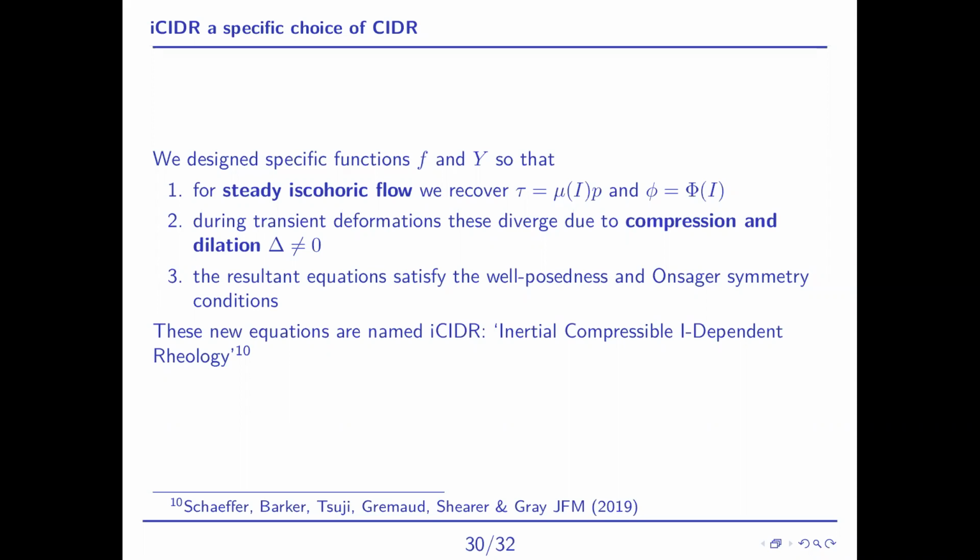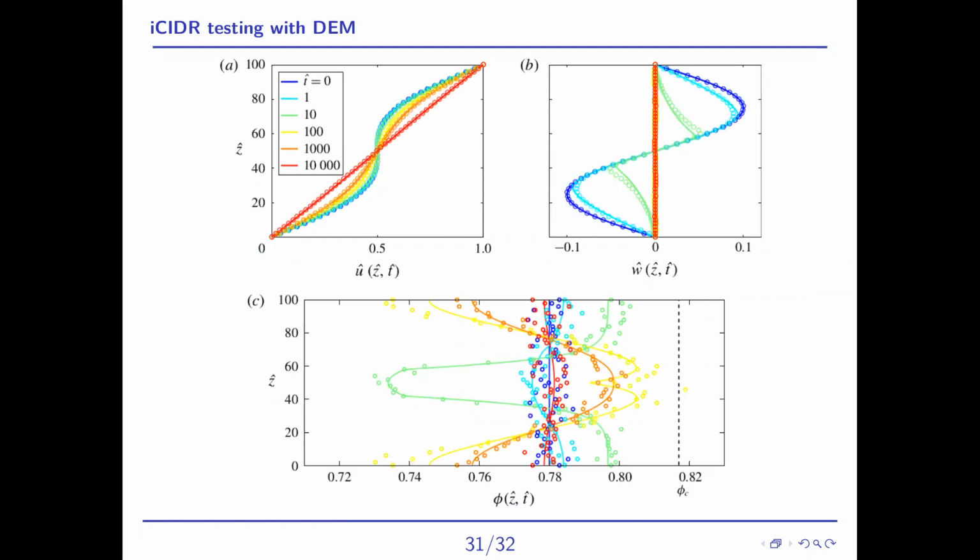And so we just cooked some up that had all these nice properties and solved those in a time-dependent problem where we started with some perturbed initial conditions, some sinusoidal function for the velocity, I think it was, at time equals 0, the two velocity components. And we compared that to doing exactly the same procedure in these particle simulations as well. So we got our particle simulation, all the particles shearing, and we then replaced all their velocities with these perturbed forms. And then we watched them relax back to this simple linear shearing, the simple shear box.